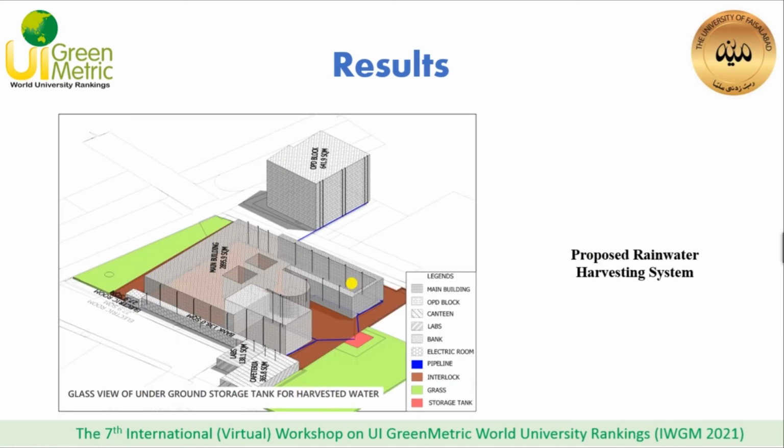This is the proposed rainwater harvesting system. We can see in this figure that we are going to use the already installed drainage pipes that deliver water from the rooftop to the bottom; this water was previously drained into the drainage system. If we install these horizontal underground pipes and convey water by gravity flow to the proposed storage tank, which will be installed at the playground in the university, then this huge amount of water can be saved and preserved for use.